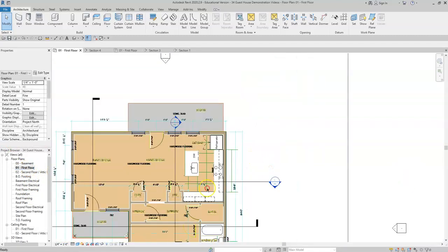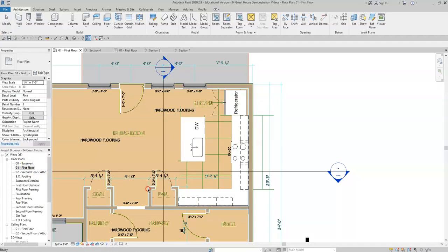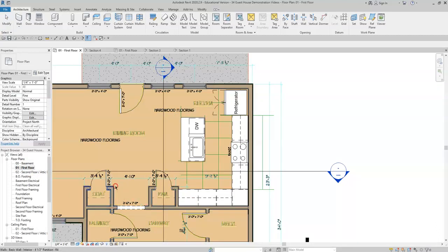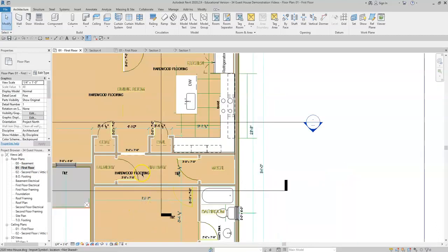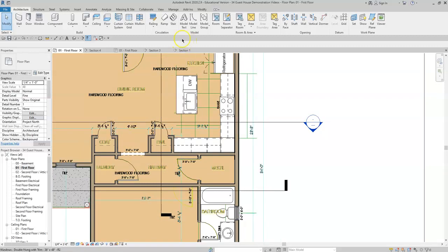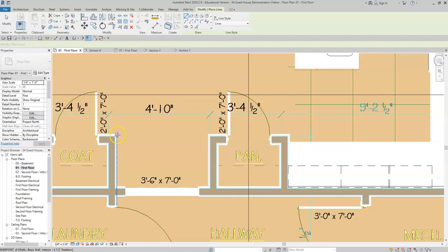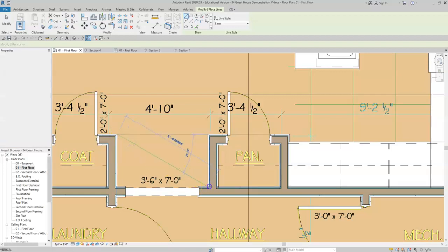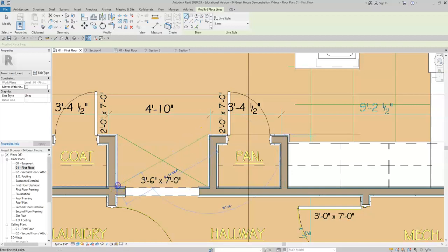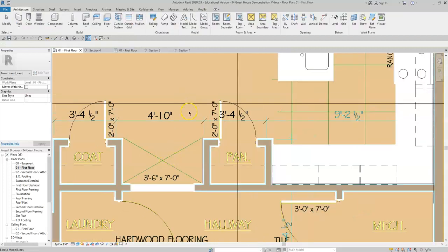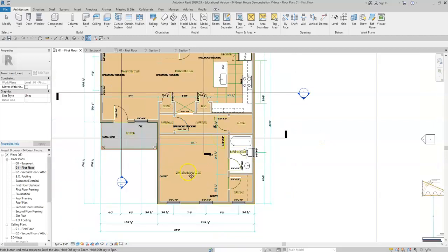If you want recessed can lights, let's say right here on this little entryway, you'll put a couple in the hall. The best way to do this is to model line and just go across the space with a diagonal line. There's 1 and 2, and then this location where it crosses will be where you put the light. So you can continue with the recessed cans.